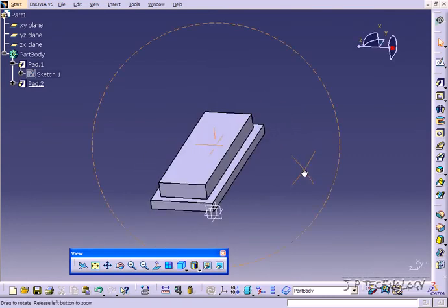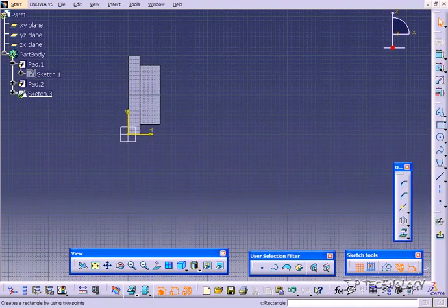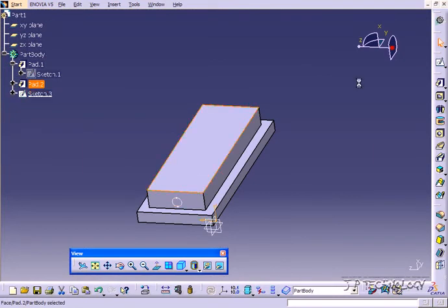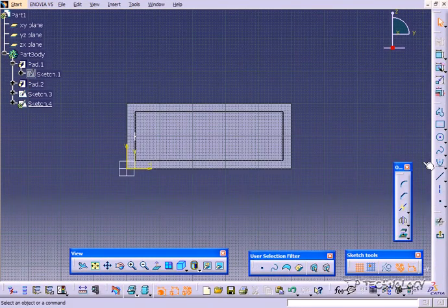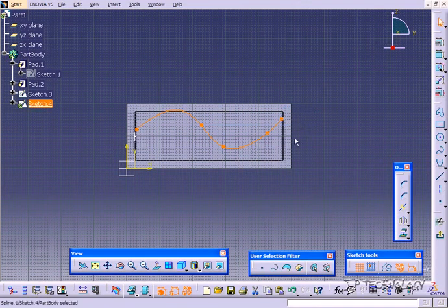and this time let's create one that isn't a square. So let's do a circle like we did on the last one. So let's click this face, click sketch, and we'll click circle. Just draw a little circle in there, and we'll go back, click the top face here, click sketch, and as we're going to be able to cut through this, we can make a route for it to follow. So if we use the spline tool, you can make a little path and a little route, and everything's going to follow and cut right through it. When you're doing this, this can be like tubing or piping that you want something to follow through.